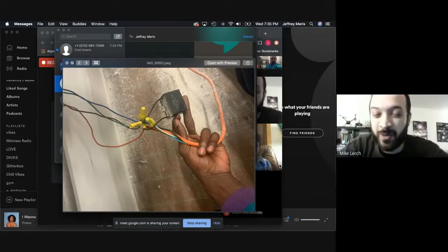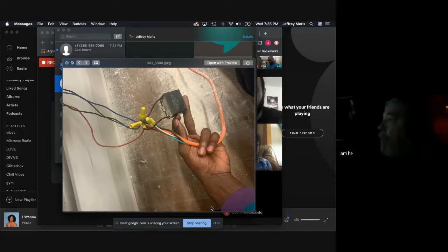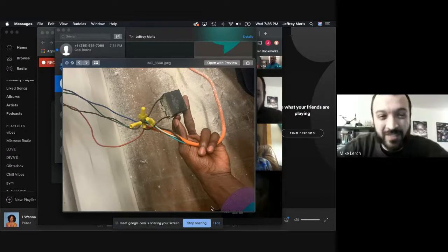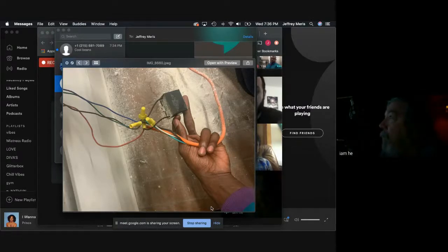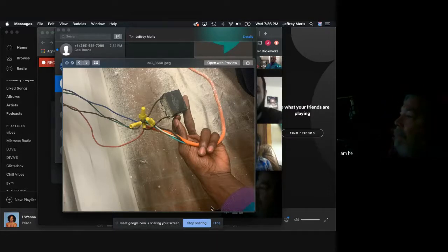Okay. So then we would certainly need to take a step up a little bit and go from something like an NPN transistor to a full-blown relay. Down to a Triac, solid state switch. Yep. Triac. You would use the Triac; it would act like the transistor, only it'll do it for AC. So you think of the Triac as like an AC transistor, a small amount of change in current will control a large amount of 120 volt current. And a Triac would do it.